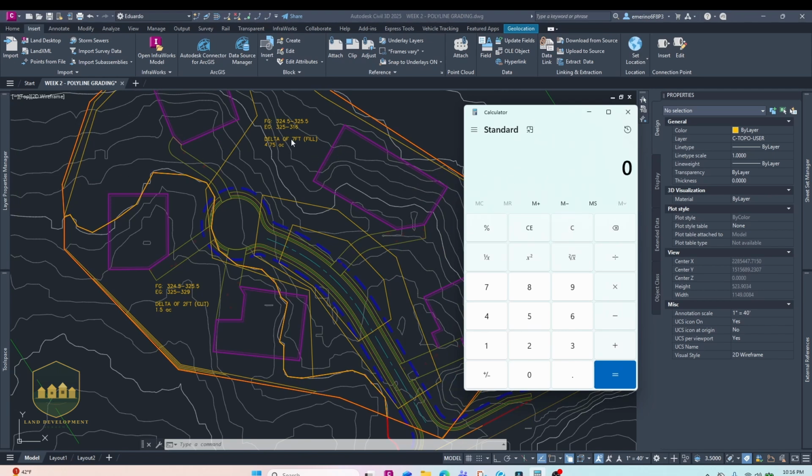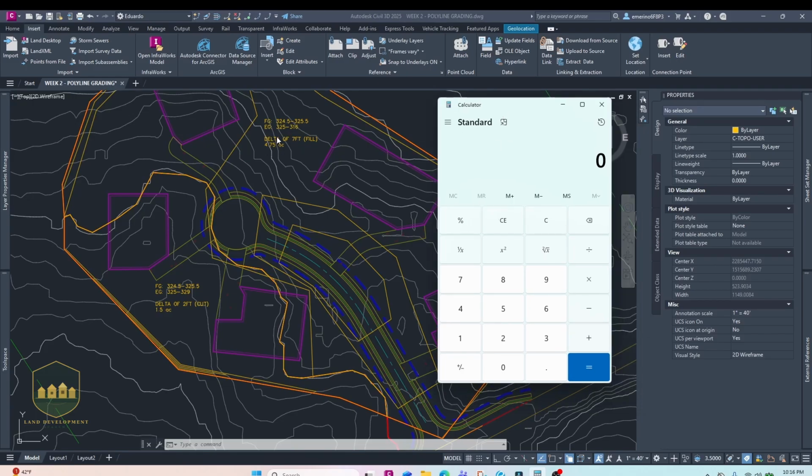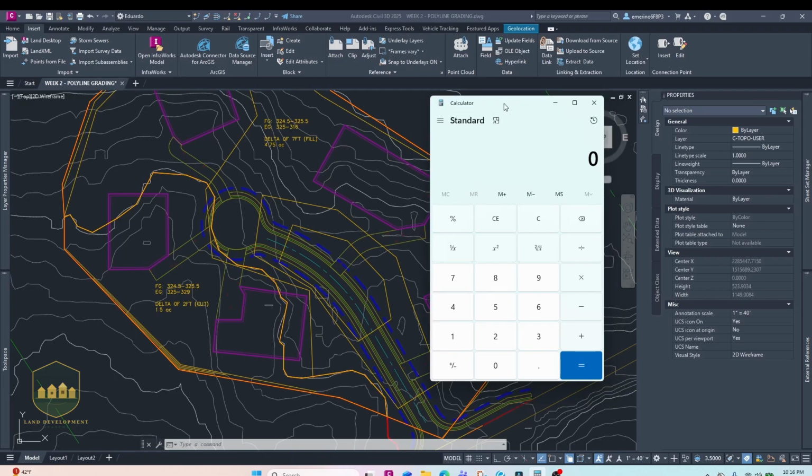So if I change this delta from 7 to, let's say, 4, then let's try it out. What if we lower the road by 4 feet? Will that get us there? So now I'm multiplying 4.75 acres times 7 minus 4, which is 3, and it'll get us 14.25.